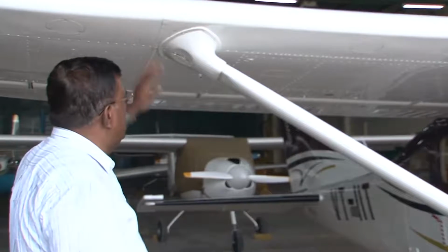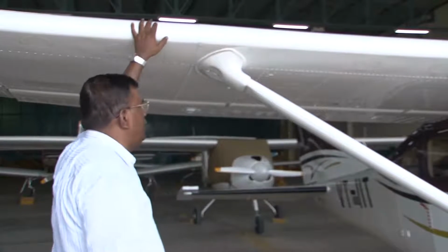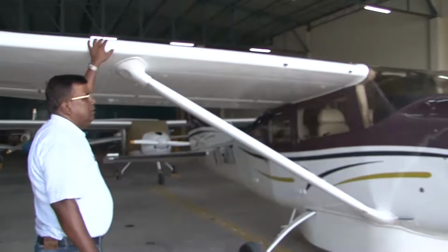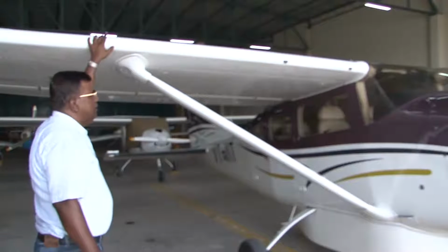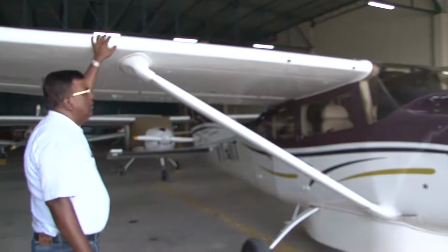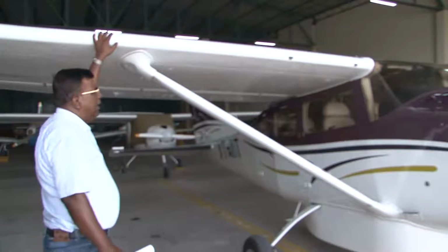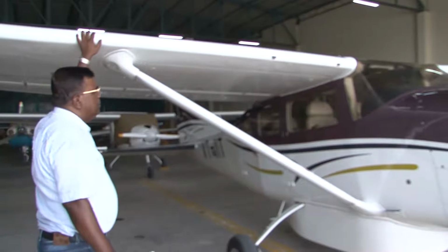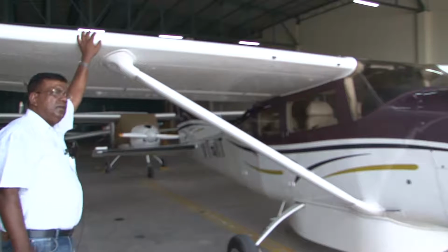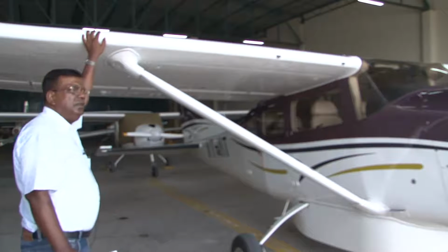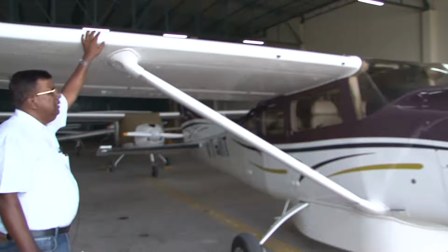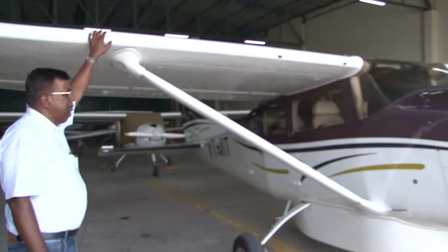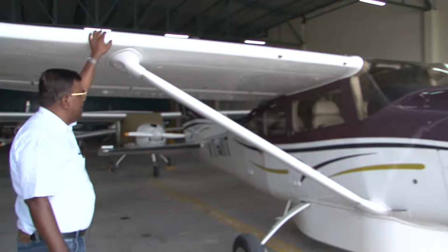Right? So once I am trying to see this wing, you will realize why I am also looking for wing setting angle. During our stability analysis, we will see that wing setting angle will play an important role in generating lift and control characteristics. So generally, if you are doing a conceptual sketch, it is better to keep 1 or 2 degree wing setting angle, and then in the final design you may or may not give wing setting angle, depending upon your requirements, right?